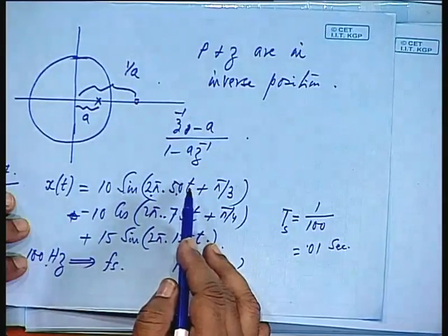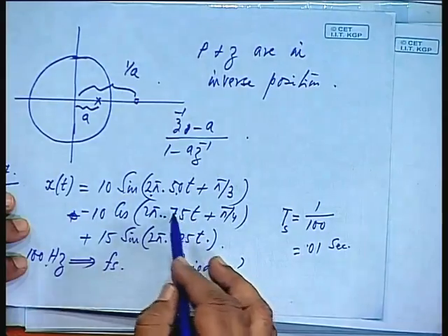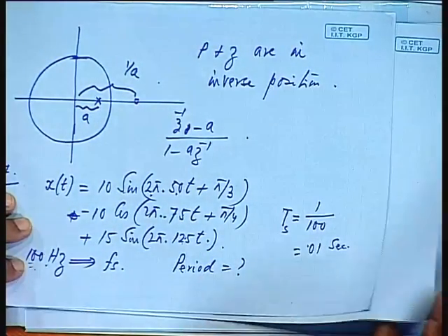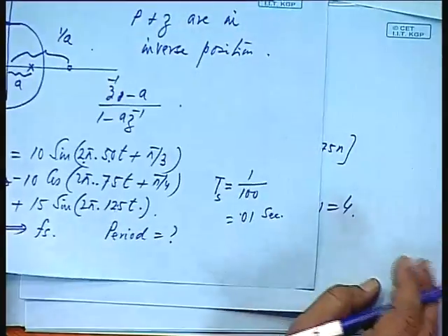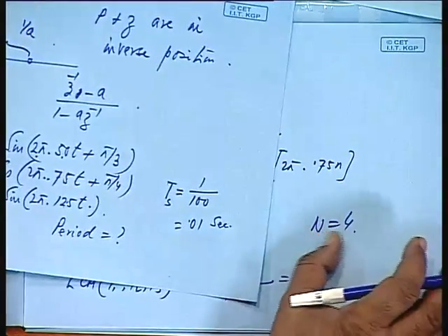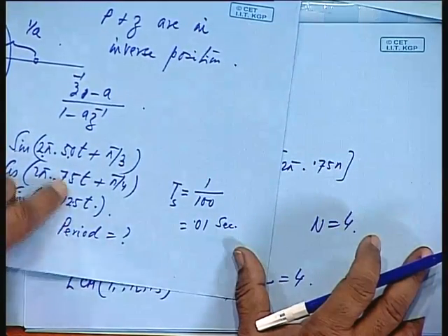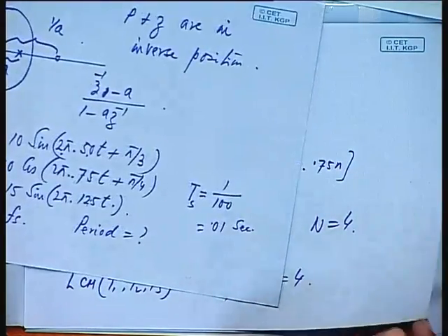This is just meeting the requirement of that Nyquist criterion. For the other two signals, this is not meeting the requirement. So, you will have a period that does not reflect the components that will be contained in the signal. To recover the original signal, what should be the frequency of sampling? At least 250. Is that all right?